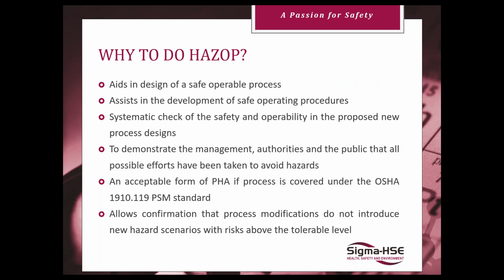Okay. All right, so why do a HAZOP? In the US, if you're handling over 10,000 pounds of flammables, or if you have a material listed in Appendix A of OSHA 1910.119 over the threshold quantity, you're required to have a PHA, and a HAZOP's a good method. Even if you have a process where you're slightly concerned, it's a new process to your facility or you're dealing with a chemical that you're not used to, it can help you design the process in such a way that it's inherently safe.